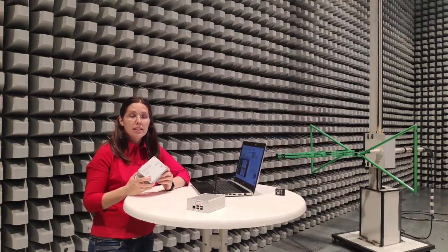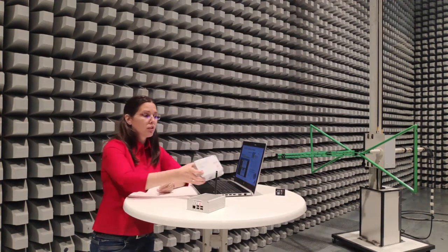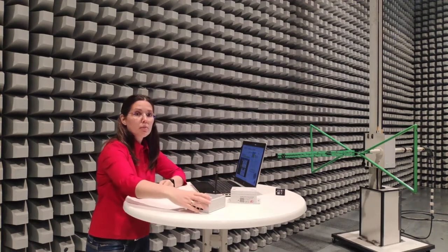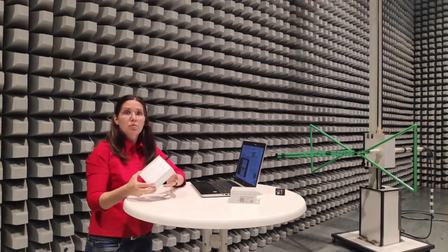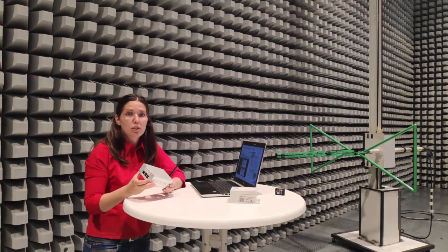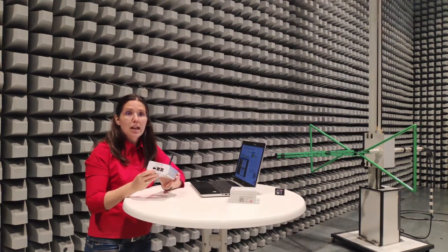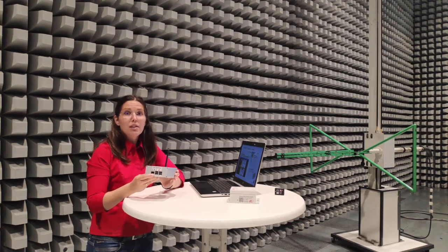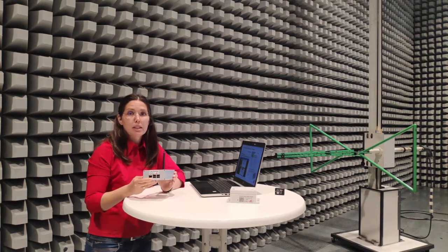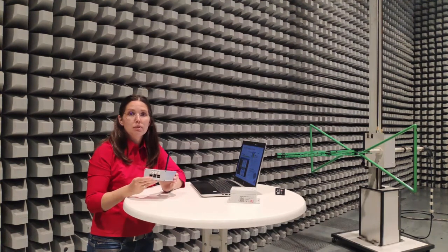Once you have your end device ready and the LCTT tool installed on your computer, you should configure the LoRa packet forwarder available in GitHub on your LoRaWAN gateway. For this, basically everything you need is to connect the gateway to your computer using the Ethernet cable and connect it via SSH for its configuration. Or even easier, the LCTT has been updated to provide a remote configuration of your LoRaWAN gateway to ensure that your setup is compatible for a successful execution of the test.